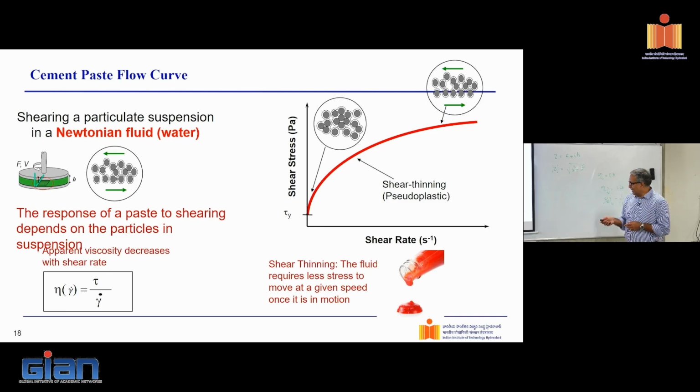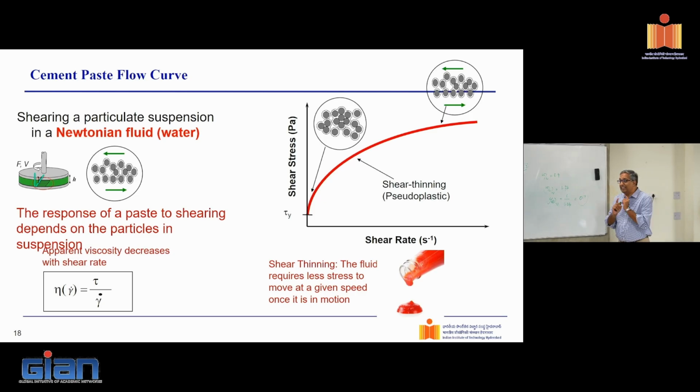And you know the common example of ketchup, right? Try to pour a ketchup out of a bottle, good luck. The best way to do it is to simply tap it, vibrate it, agitate it. The more you agitate it, it becomes more and more fluid and it starts to flow, right? That's exactly what we get in cement paste. It's shear thinning. So it is a material that has a yield stress and is shear thinning. That means if I agitate the material, it will flow easier.